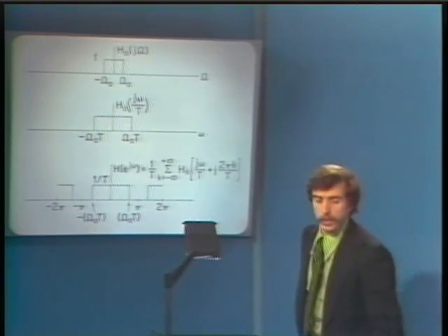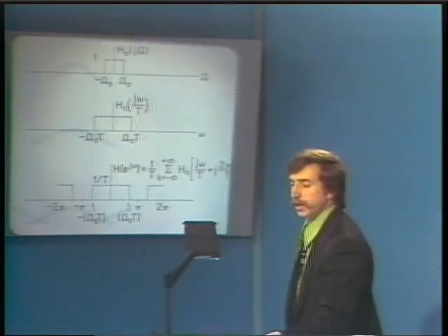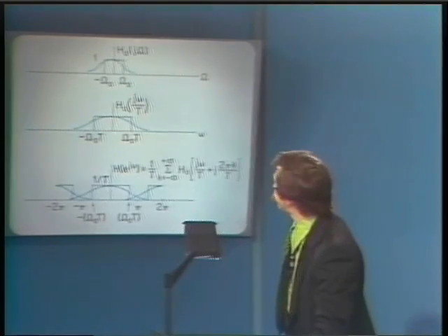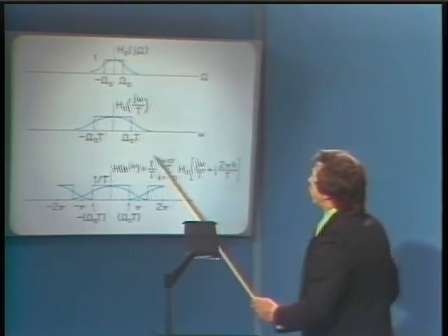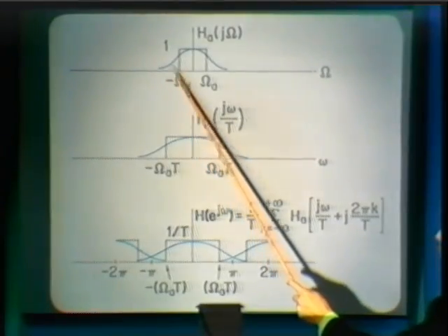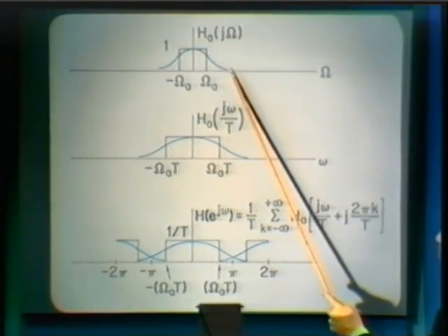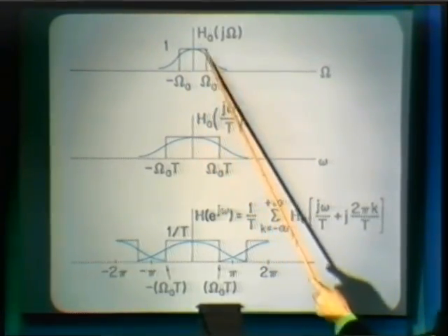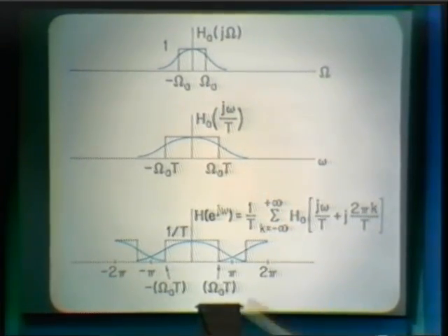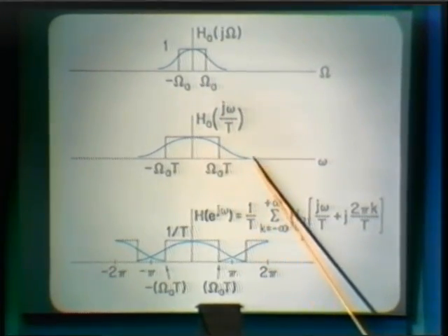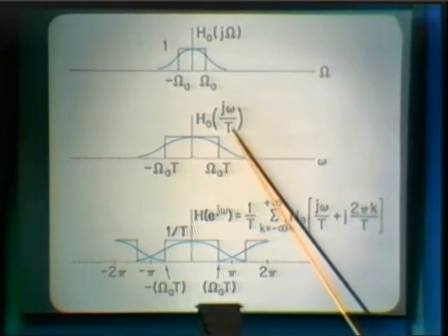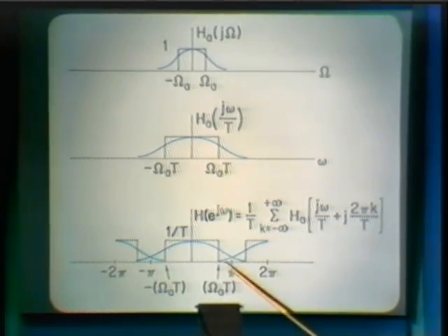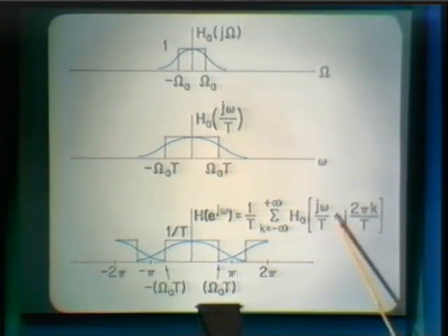But more generally, the kind of frequency characteristic that we would have would look perhaps like this, as an approximation, admittedly a somewhat crude approximation, to this ideal low-pass filter. In which case, as we add up the replicas of the scaled frequency response, we, in general, will have interference or aliasing between different terms in this sum.